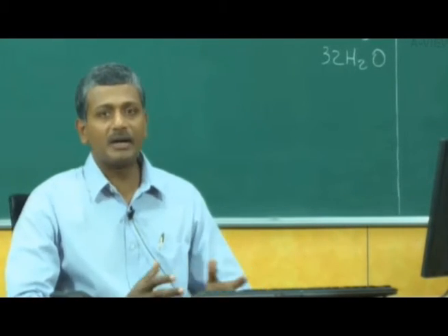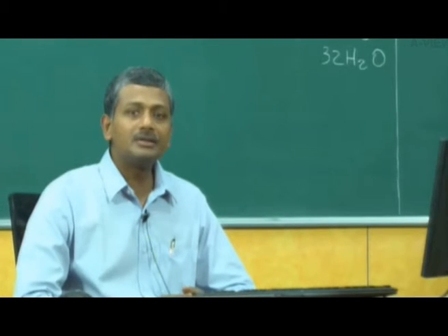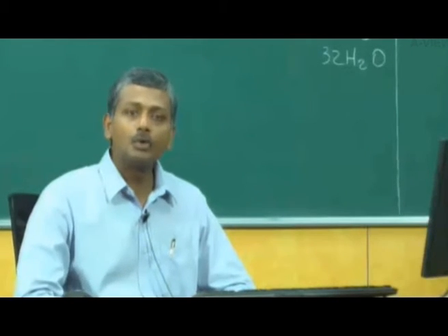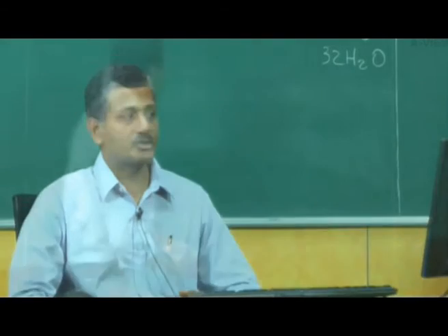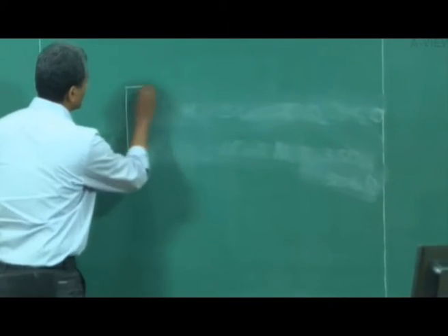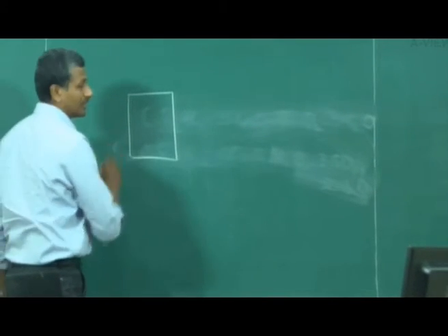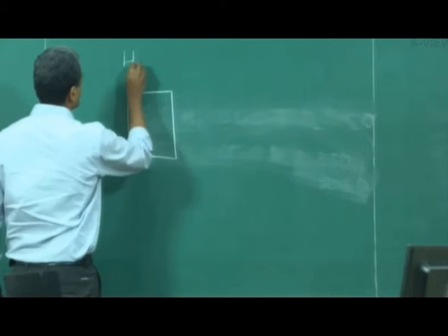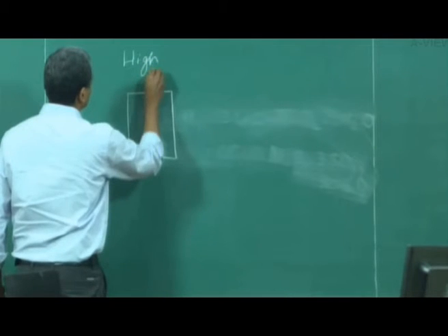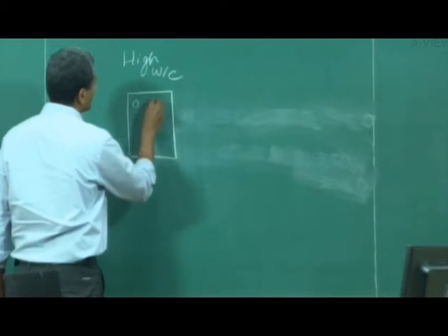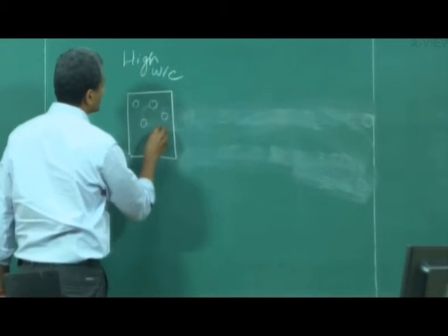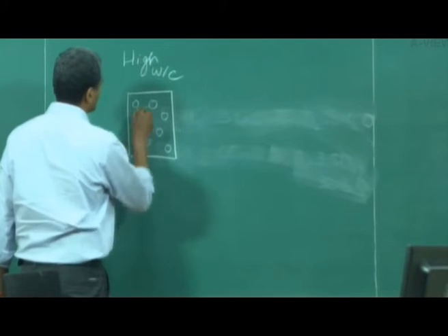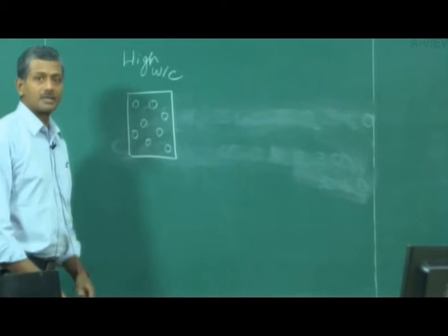So I will show you a schematic just to help you rethink your understanding of how you produce high strength or high performance concrete. Now, let us assume this is my volume that I need to fill up with my mixture of cement and water. So in a high water cement ratio system, I have a lot of water present along with the cement.